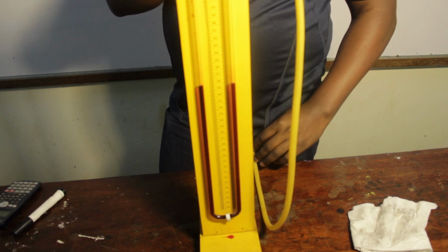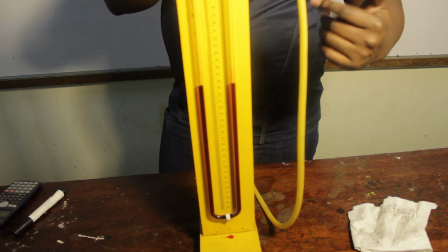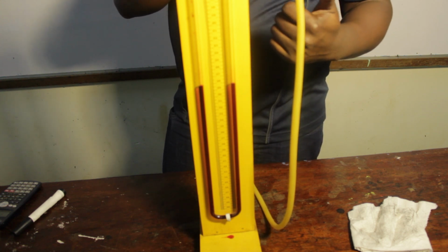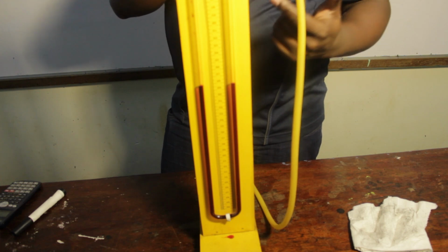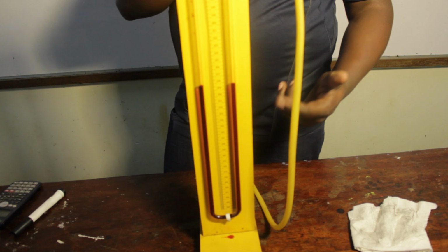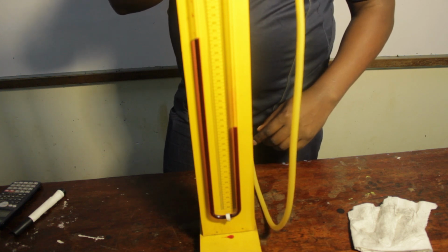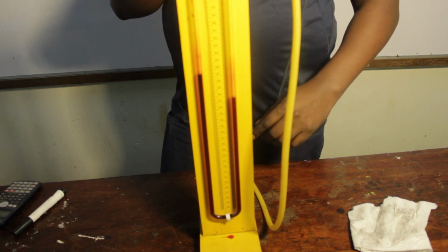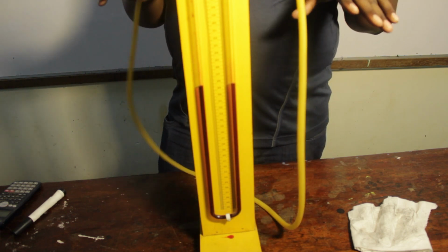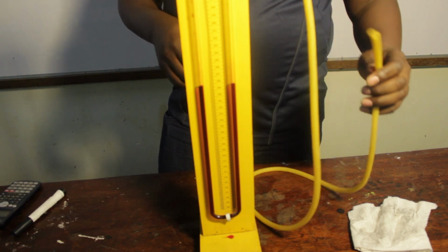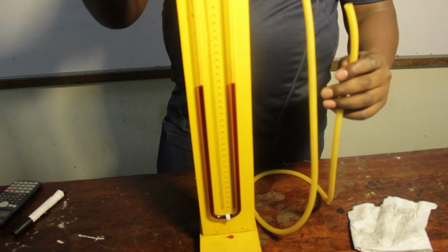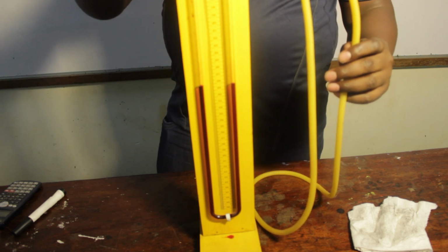So for us to know the pressure difference, we simply get the difference in heights. Get the height on the higher side minus height on the lower side, then multiply by density of this liquid, which is colored water. So we shall just use 1000 times 10. When I withdraw the pressure, you can see that the liquid goes back to the same level. This is because the pressure being felt at the tip of this tube is the same pressure acting on the open side of this U-tube.